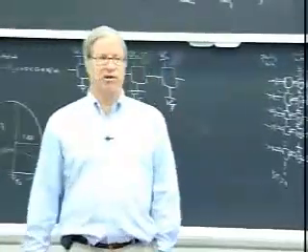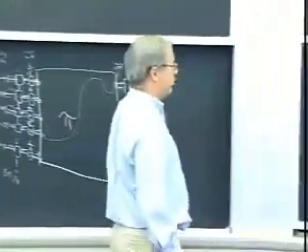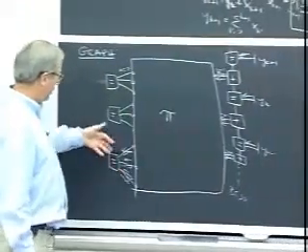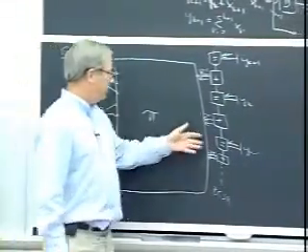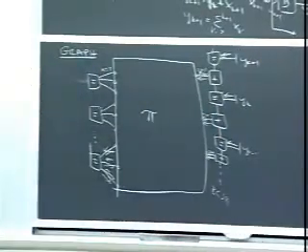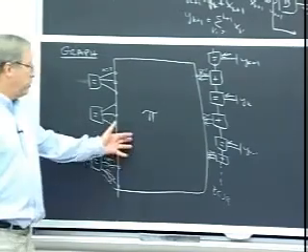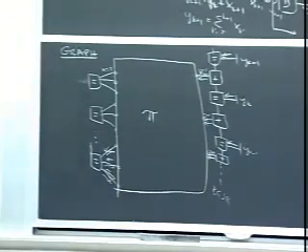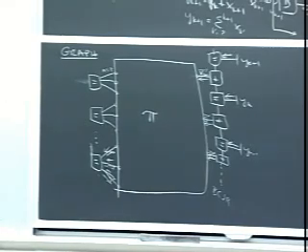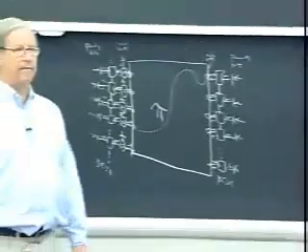This is the moral here, that even this incredibly simple code, where nothing is going on, where all we have is binary state variables, equals and zero-sum nodes, that's it, it's made out of the simplest possible elements, even this code can get within a dB or two of channel capacity. And I'm old enough to know that in 1993, we would have thought that was a miracle.